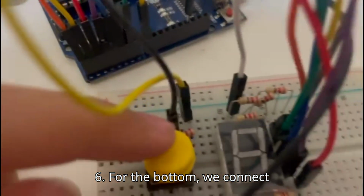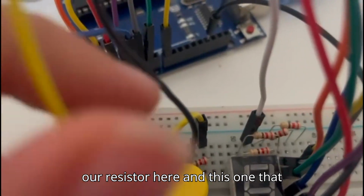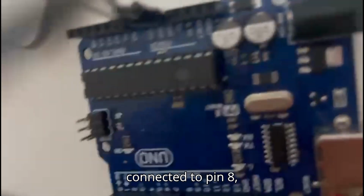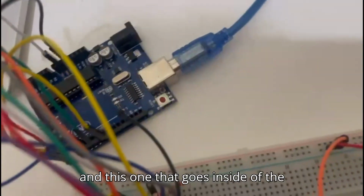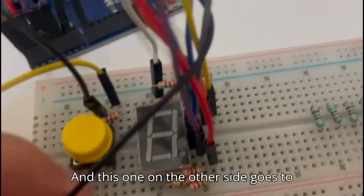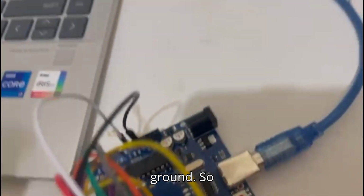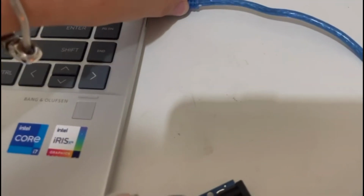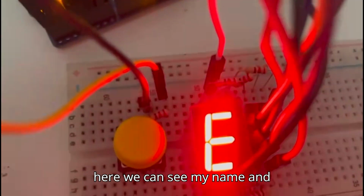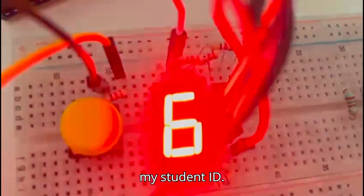For the button, we connect a resistor here, and this one that goes outside of the button is connected to pin 8, and this one that goes inside of the button we connect to voltage, and this one on the other side goes to ground. So let's upload our file. Here it is, and here we can see my name and my student ID.